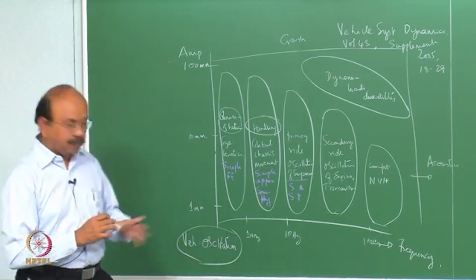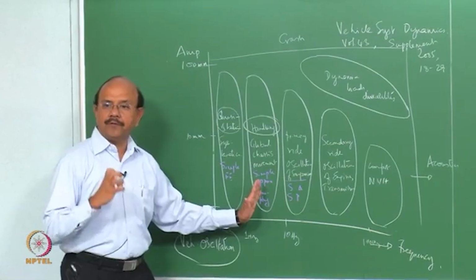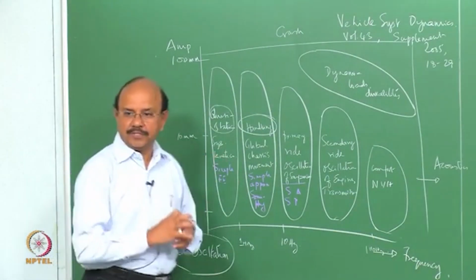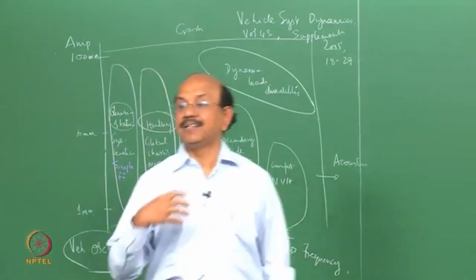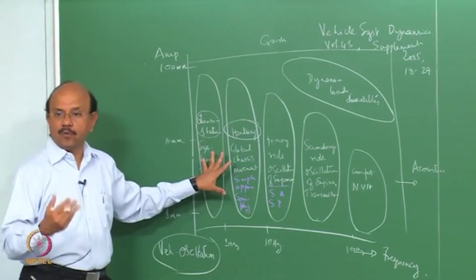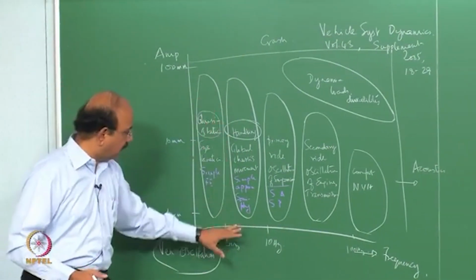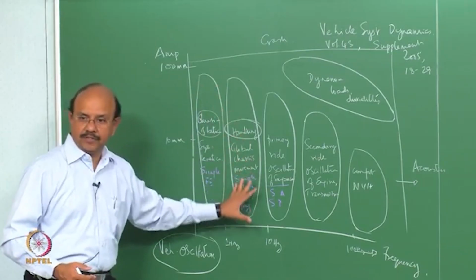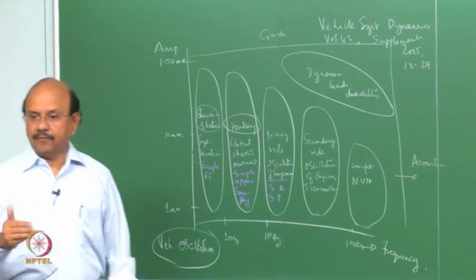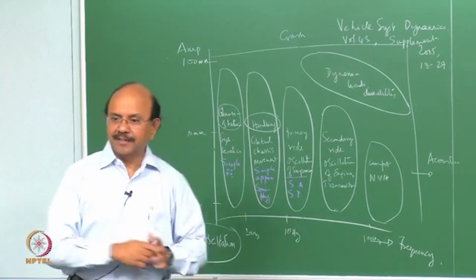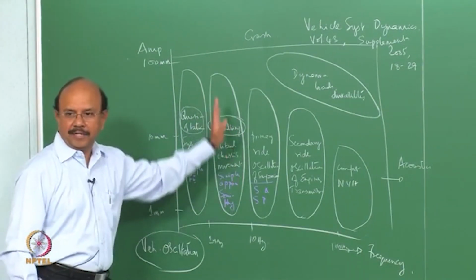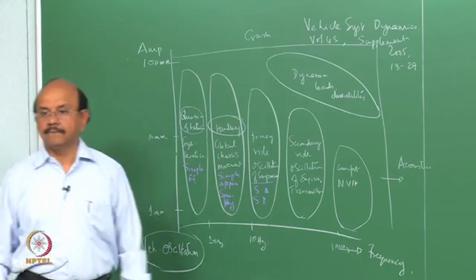You would see that we will come to this handling when we take a turn. Certain frequencies, which are the result of the whole vehicle mass, moment of inertia, and so on, are going to have a role to play. And those frequencies are in this range. The frequencies which are going to play when we look at lateral dynamics, handling, are about 4 to 5, 3, and maybe 2, 3, 4. That's the range. But the lower frequencies will also be there, right?